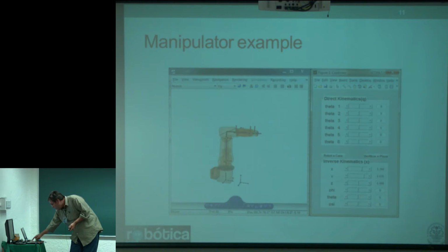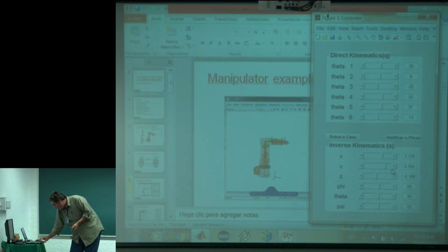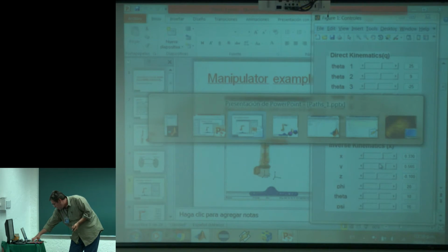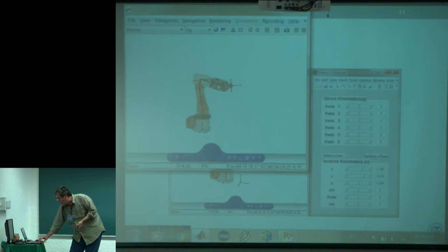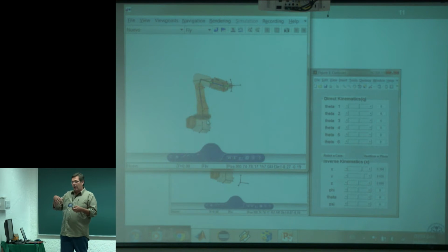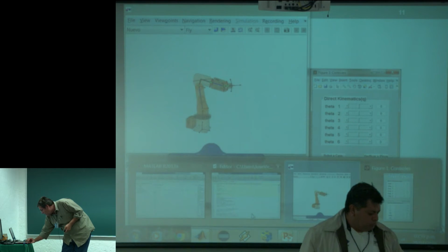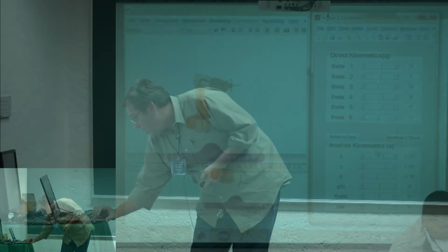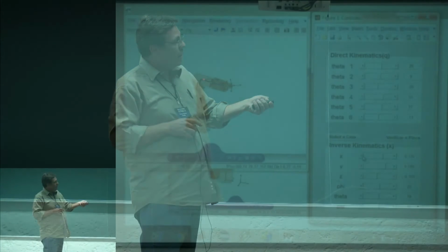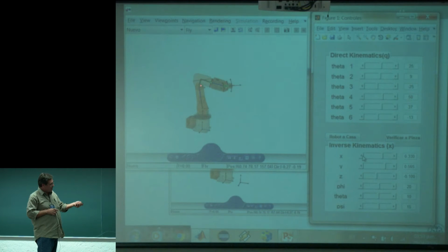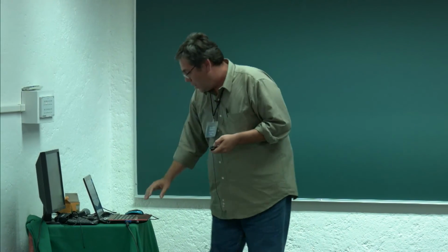So this is how this program works. We can compute the inverse kinematics of a 6 degrees of freedom robot. We have some virtual reality here, which shows the frames and allows us to present in a clear way this kind of computations. And by programming in MATLAB, we can verify our solution. There are many caveats in this solution. For example, this elbow will mean that we need this distance and we need this angle, but we can carefully analyze it, but the main ideas are those that we presented.